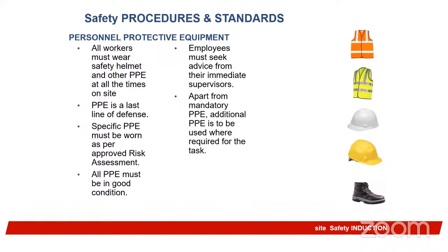So you should also communicate about the use of PPE to all the workers that you're inducting on site. I've said that it is beyond just induction. It's proper training. You train them on how to use the PPE that is required for their job. The training that you will give a welder is different from the training you will give a laborer, and different from the extra training you will give another technician, maybe a plumber, because the exposure, risks and hazards that they are exposed to are different.